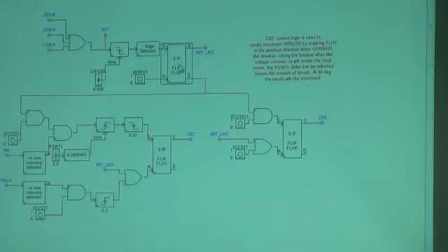These reset flip-flops essentially just emulate an 86 lockout relay. So when your relay trips, typical for a transformer, right? When transformer protection operates, your lockout relay is set and you cannot re-energize the transformer without going out and doing a physical inspection. So that's all that this logic is doing to make the simulation a little bit more realistic.